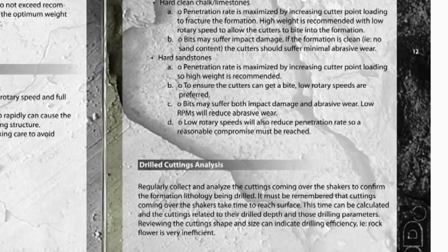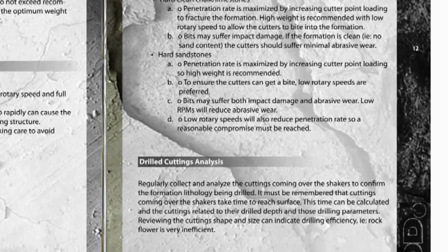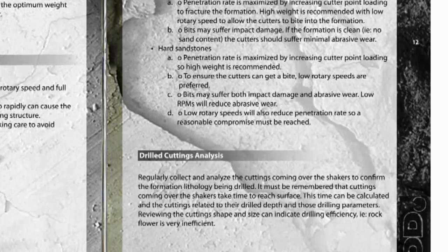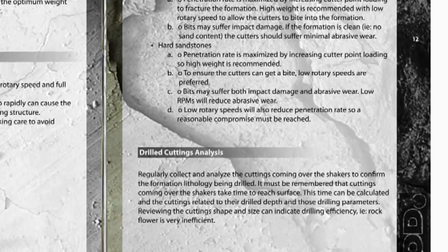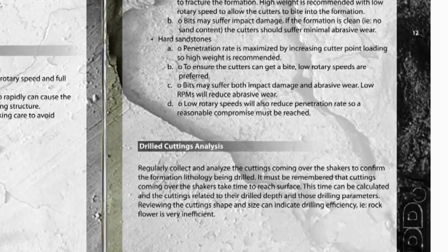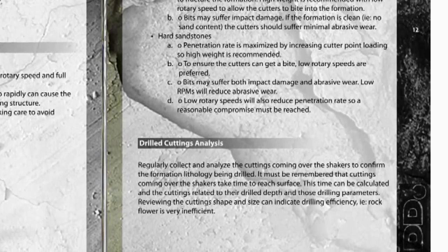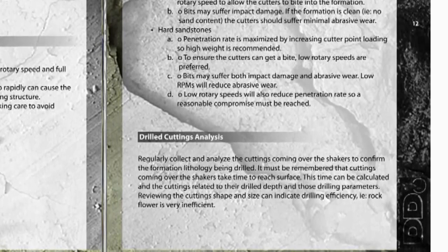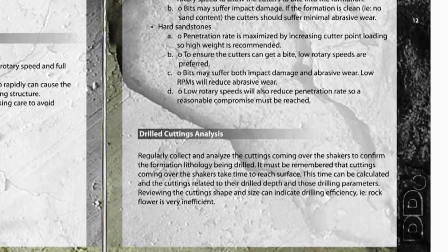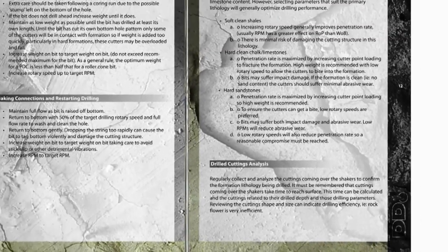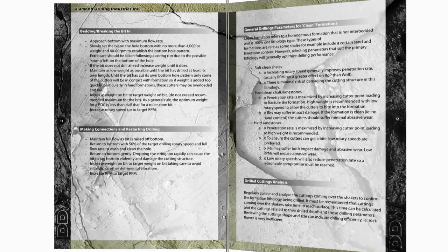Regularly collect and analyze the cuttings coming over the shakers to confirm the formation lithology being drilled. It must be remembered that cuttings coming over the shakers take time to reach surface. This time can be calculated, and the cuttings related to their drilled depth and those drilling parameters. Reviewing the cuttings' shape and size can indicate drilling efficiency, i.e., rock flour is very inefficient.